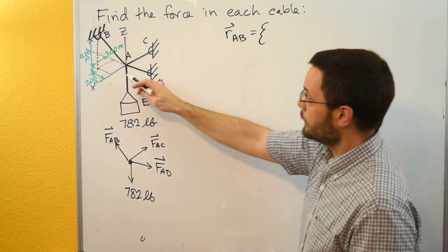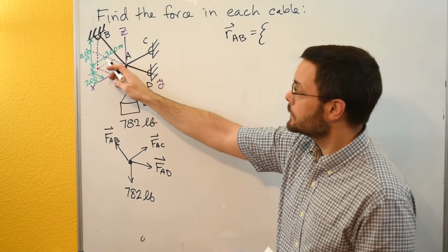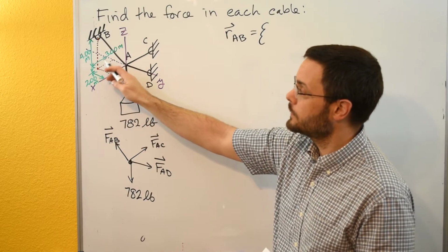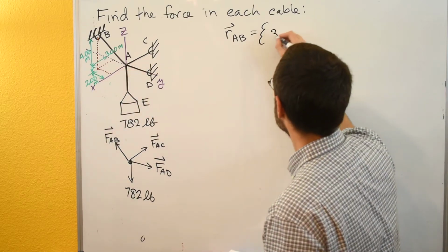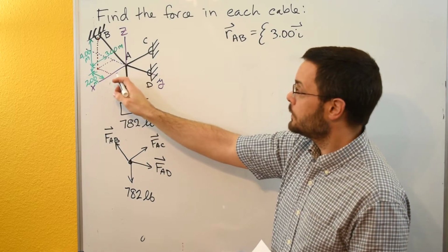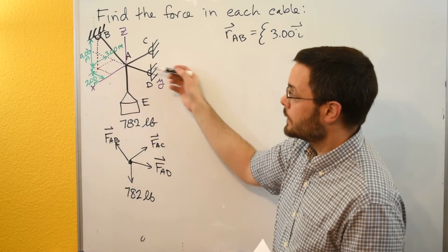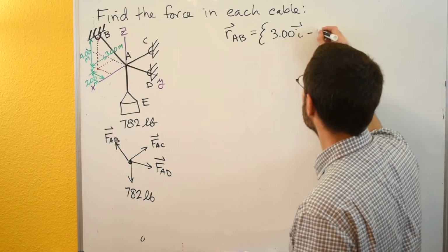So we're going, let's see, looking in X. X is in this direction. We need to look for the line with the 2 arrows on it that's parallel to that, and that's our 3. So we're coming out from the origin 3. So it'll be a positive 3i. And then we're coming out from the origin 2 in the y direction, but it looks like it's moving in the negative y direction. So it's going to be a negative 2j.